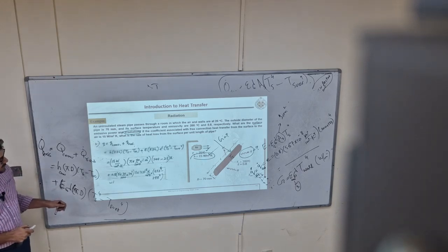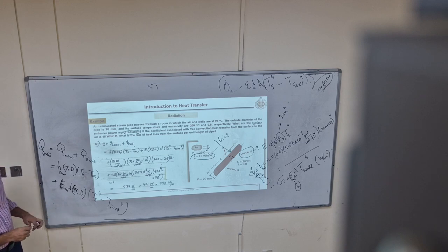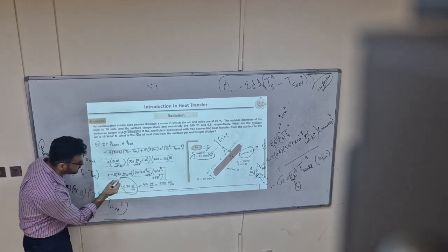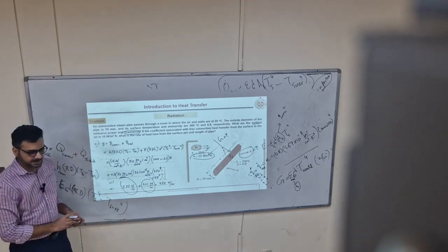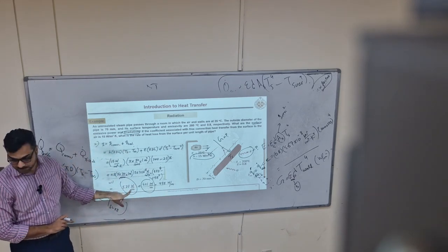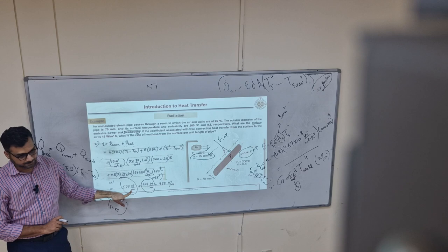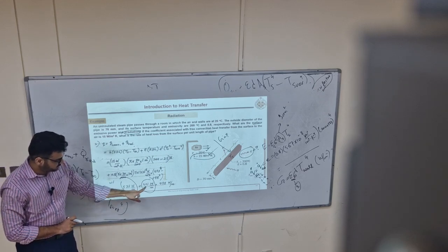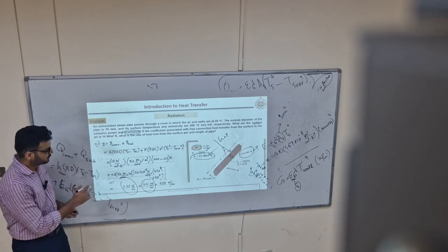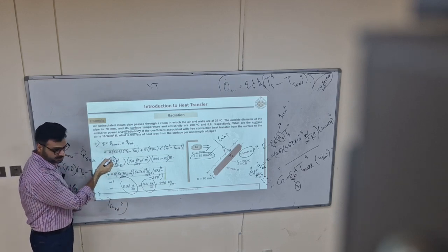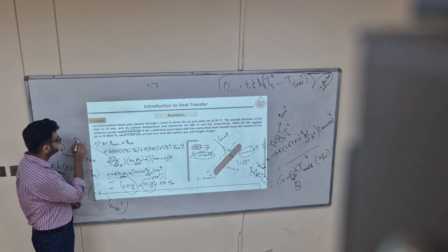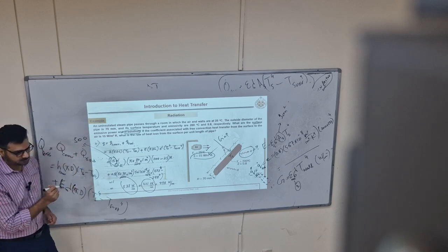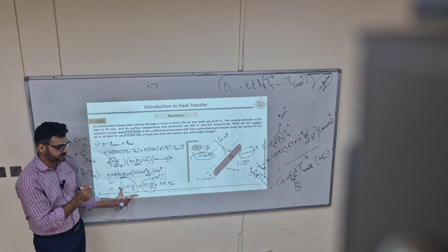So you can see the heat loss here. This is the convection part. This is the radiation part, in watts per meter of unit length of the pipe. Look here, it was natural convection. That's why those are comparable. Now just assume forced convection. Let's make it 500. So you will see this part will reach thousands.